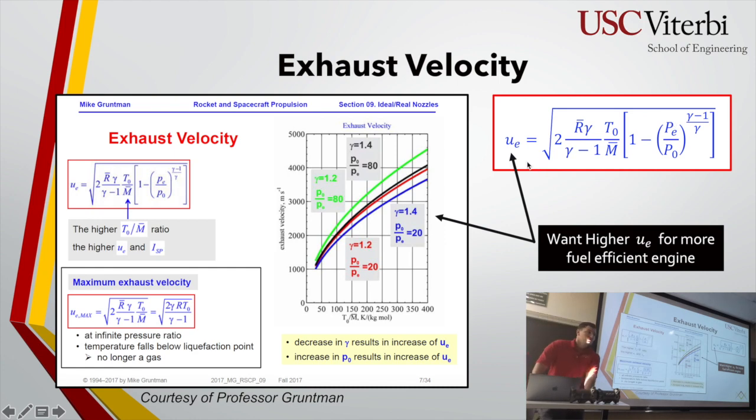How close to 1 can we get gamma? That's a good question. I would not know that off the top of my head. Someone else maybe? Depends on what kind of molecules you're looking at. Gamma is basically kind of like the internal kinetic energy contained by the molecules. Say the molecule has multiple atoms inside, the gamma will be greater. If it just has 1 atom or 2 atoms inside, the gamma will be smaller. But the rough number is usually from like 1.2 to 1.8 something. I've never seen something above 2.